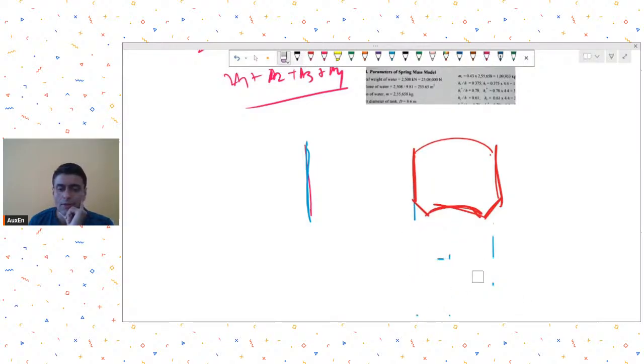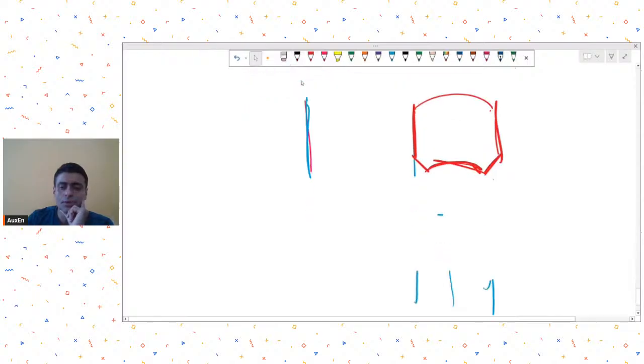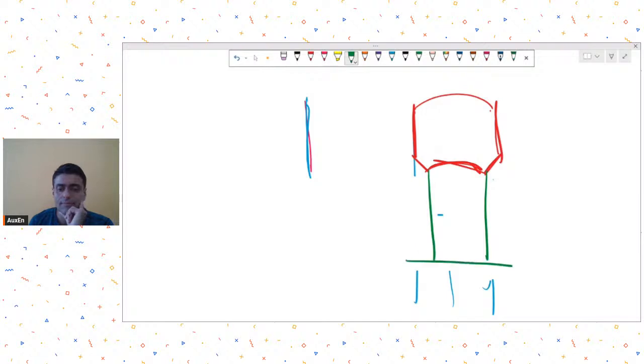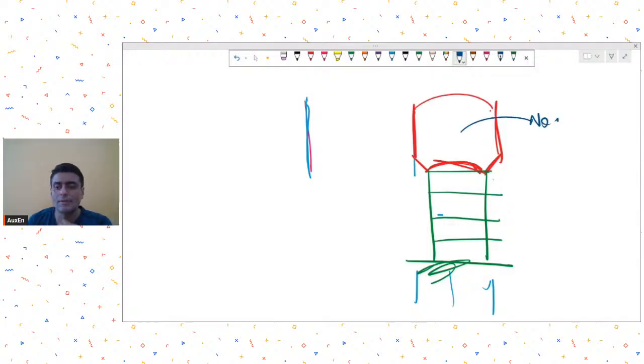Once you calculate the shear force, this is my staging. In the STAAD model, no need to model the tank. You just make the staging, and then make a rigid link or a very stiff element over here.